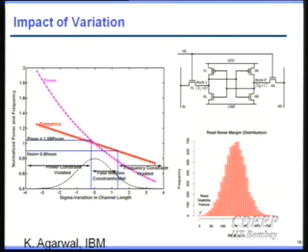So let's look at the impact of variation also from the memory point of view, and I'm not going to spend too much time here, but it turns out memories are going to be more important than the logic. The reason is that I'm going to be using transistors which are smaller in terms of width, and hence, due to higher integration density, we can see later on that the read noise margin varies quite a bit.